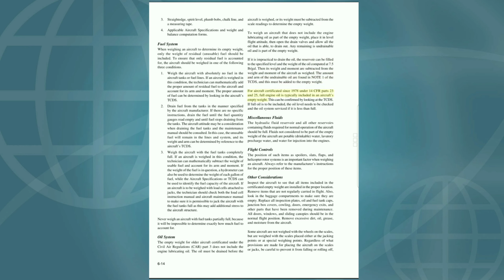For aircraft certificated since 1978 under 14 CFR Part 23 and 25, full engine oil is typically included in an aircraft's empty weight. This can be confirmed by looking at the TCDS. If full oil is to be included, the oil level needs to be checked and the oil system serviced if it is less than full.